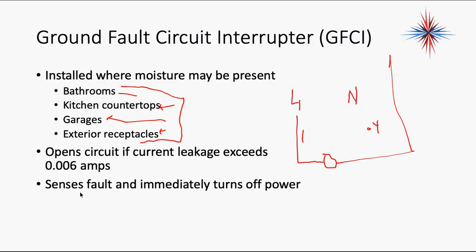Not the best idea in the entire world, but because it's a plug, because it's on a concrete floor, and because there's moisture around it, we sometimes plug those into an outlet. So the condensate pump might not be bad. It might just have had a trip on the GFCI breaker. It happens on occasion. You reset the GFCI and life goes on after you clean up the puddle of water.